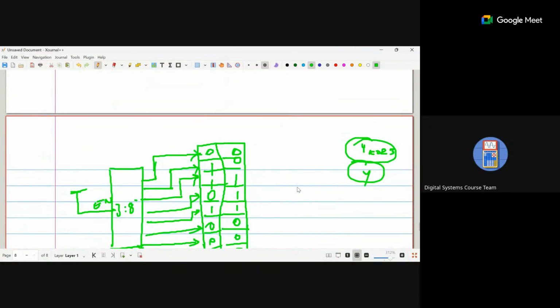So the main idea for all this is just to program the logic differently. With lookup tables, the main idea is that you use a decoder to select that particular row and give it back. Similarly, with multiplexers, you can use different kinds of multiplexers to implement Boolean functions.